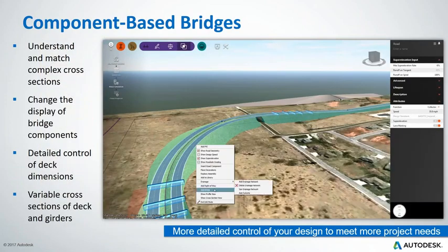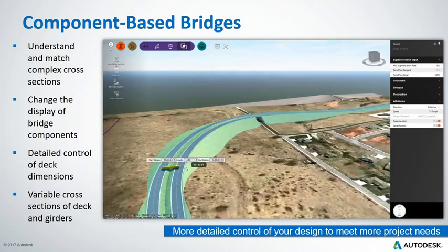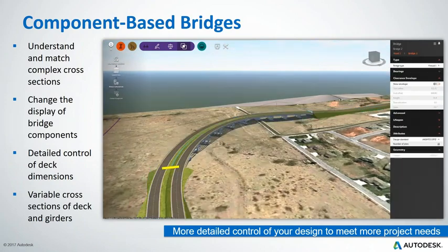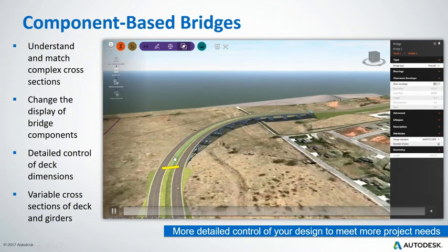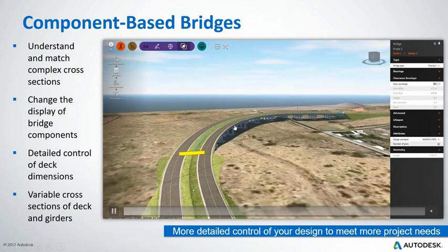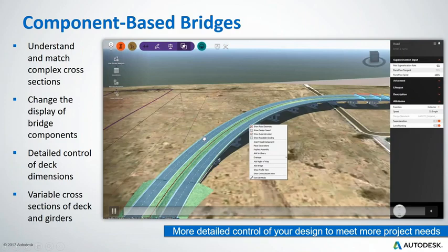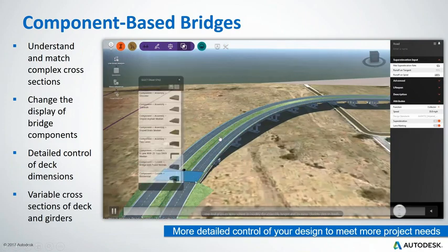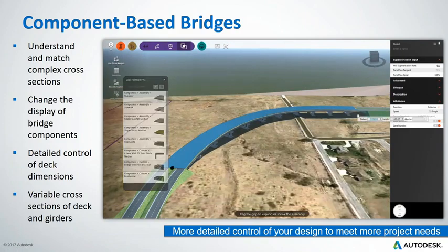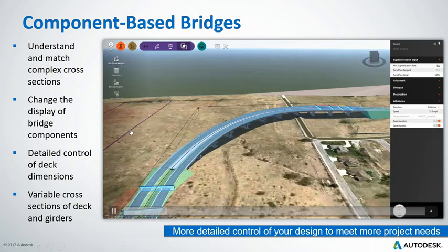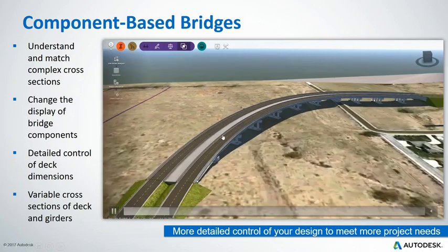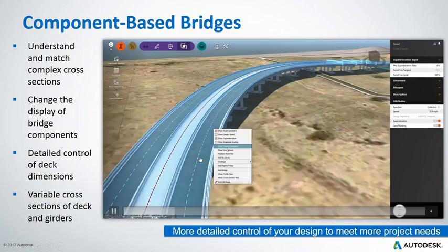Now, with the latest releases of InfraWorks, the product management developed something called component-based roads. These component-based roads are also very useful for bridges. So with a single click, these component roads will understand that this is a bridge underneath, and they will actually adopt the same road style of the road to that bridge as well. Now you can definitely change that style at any point in time. We've here changed just the median by selecting an assembly from the library.